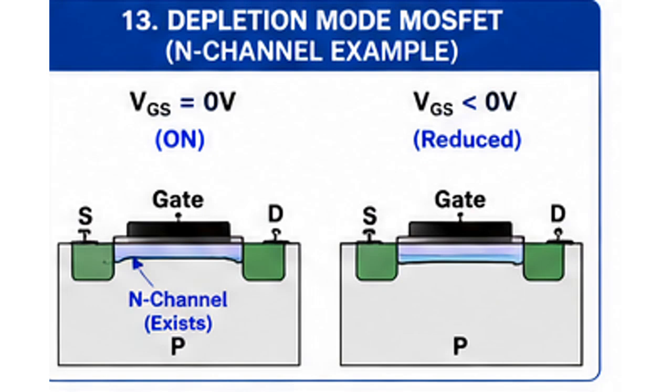When the gate-to-source voltage exceeds the threshold, typically a few volts for a logic level device or more for a standard power MOSFET, the channel forms and the LED lights. Remove the gate voltage or pull it to ground and the LED turns off. Use close-up views of each connection so that every terminal is clearly visible.